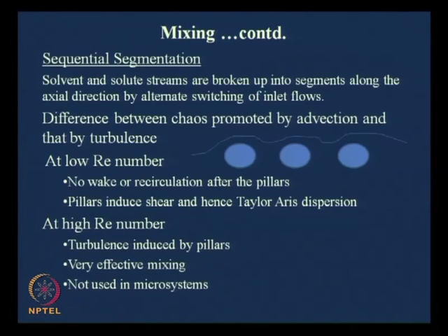Next topic that I pick up is sequential segmentation, where solvent and solute streams are broken up into segments along the axial direction by alternate switching of inlet flows. This I am going to discuss very soon, but before that I would like to point out the second thing that I have here, which is the difference between chaos promoted by advection and that by turbulence.